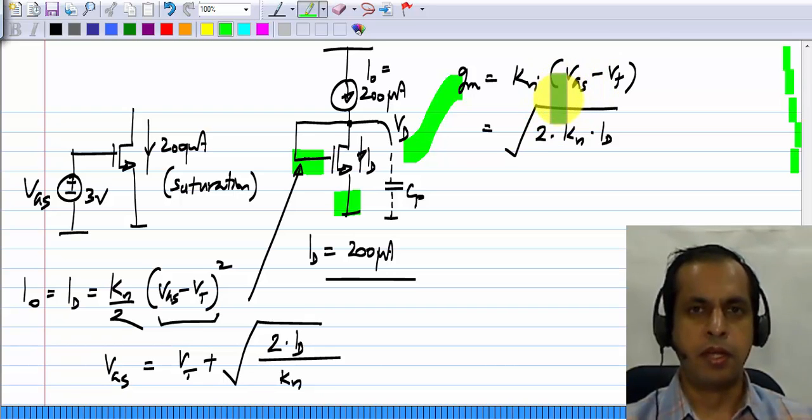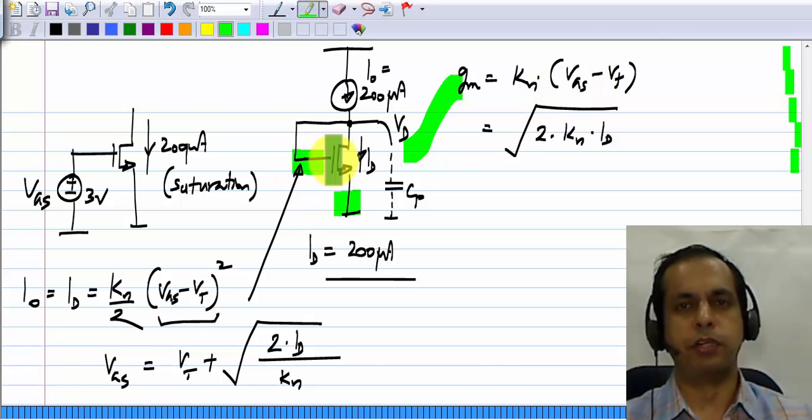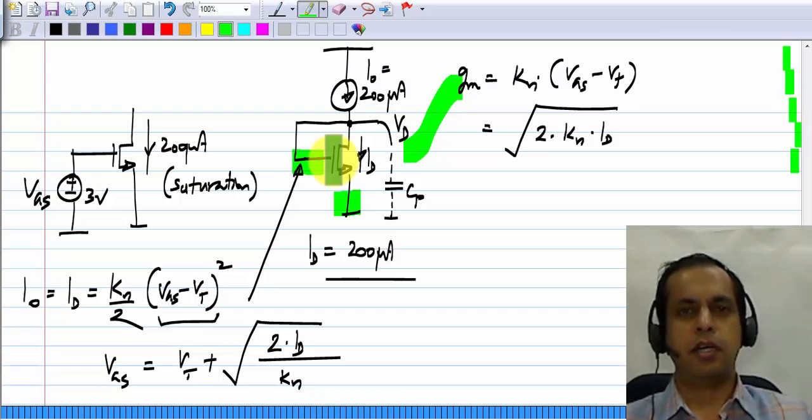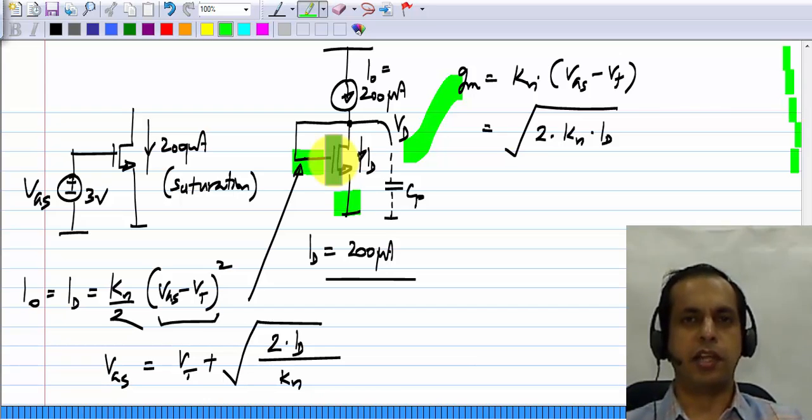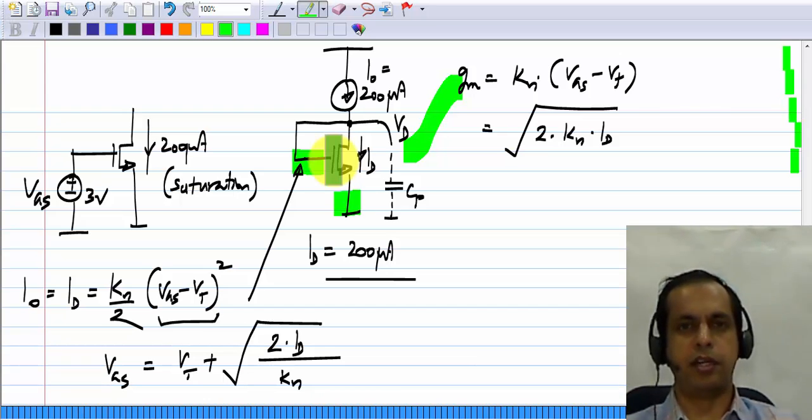Is this okay? So essentially, this negative feedback is a way of adjusting the VGS in response to changes in transistor's parameters. A transistor with a higher threshold voltage or a smaller current factor will automatically get biased with a higher VGS, compensating for the effect of the higher threshold or lower current factor.